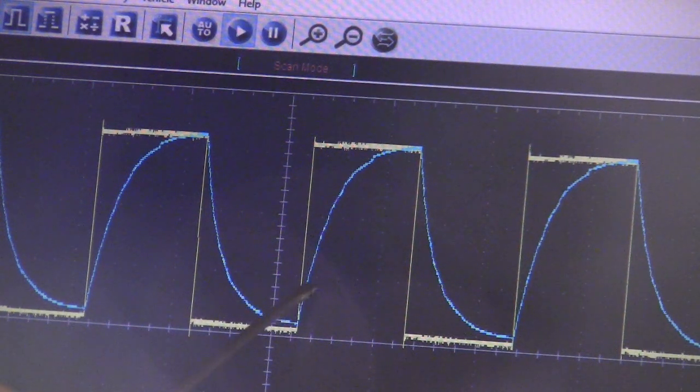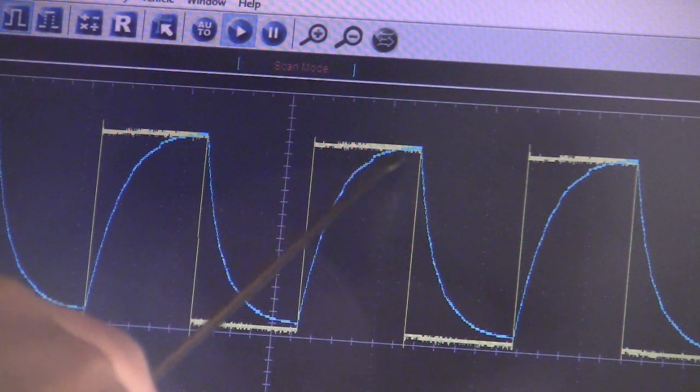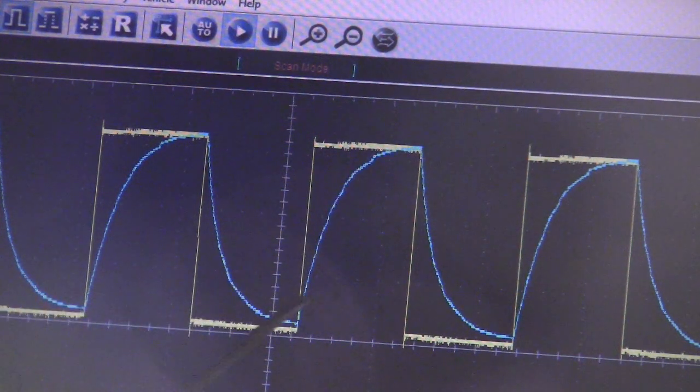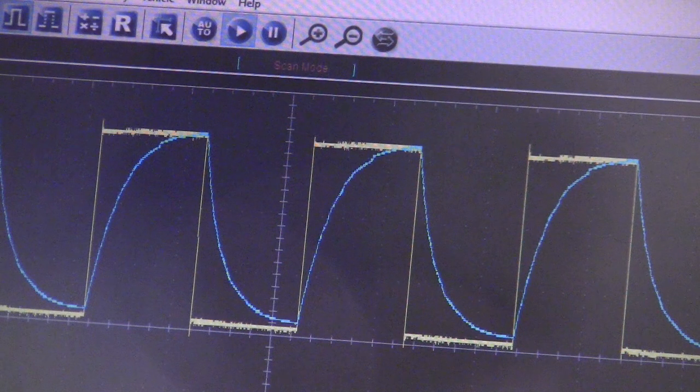The voltage rises very slowly, eventually catching up. So that means the capacitor voltage is behind the voltage of the signal. Because this is a series circuit, the current in the signal and the capacitor is the same. So we can say the capacitor voltage phase is behind the current.